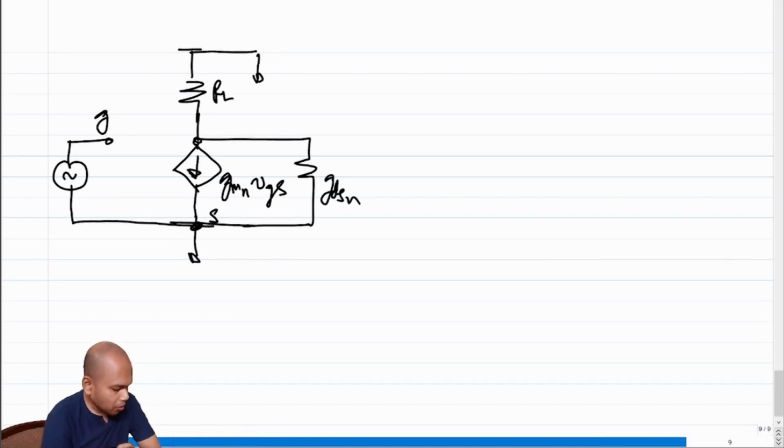Okay. So what was the whole motivation behind the search for PMOS? The whole motivation was to replace the RL with another transistor whose drain is connected to Vo, right? So this was Vo. If we can use a PMOS, because the higher terminal voltage is now a source, then in principle this is possible.